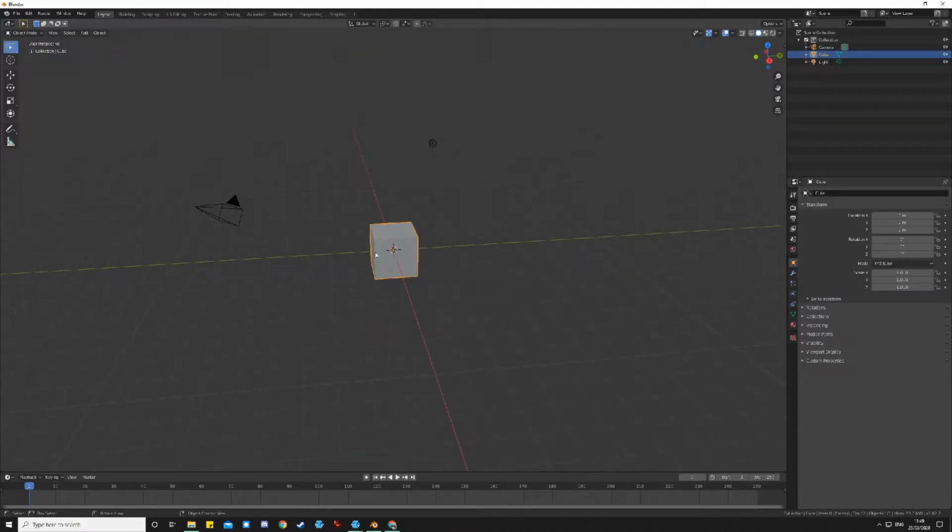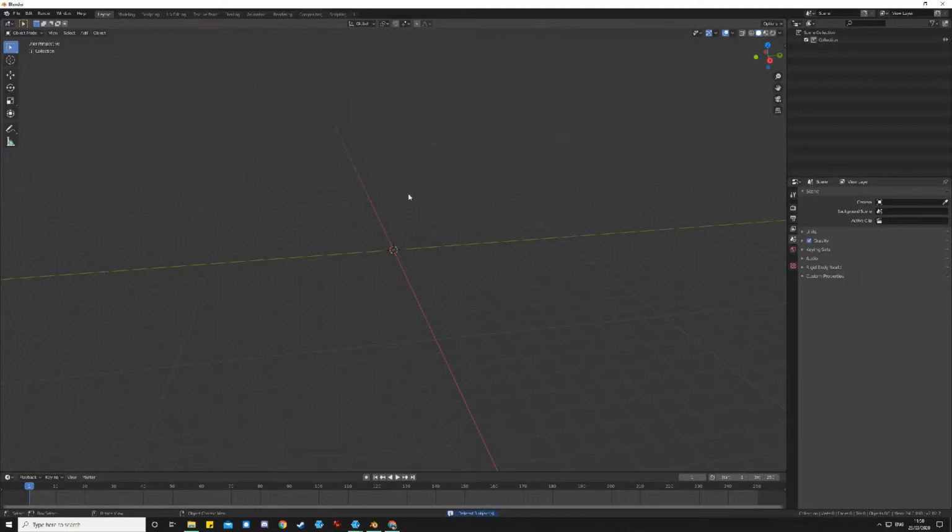And then you're in Blender, like here, and the first thing to do is we've got to import our model from Meshroom. So within Blender, the first thing that happens whenever you open Blender is you're always given a box and a camera and a light. You don't need any of this for what we're doing, so we need to delete all this to start with. So we press A, which selects everything, and then we press X, or you press delete, and you say, yes, I want to delete it, and we've got a nice clean space here.